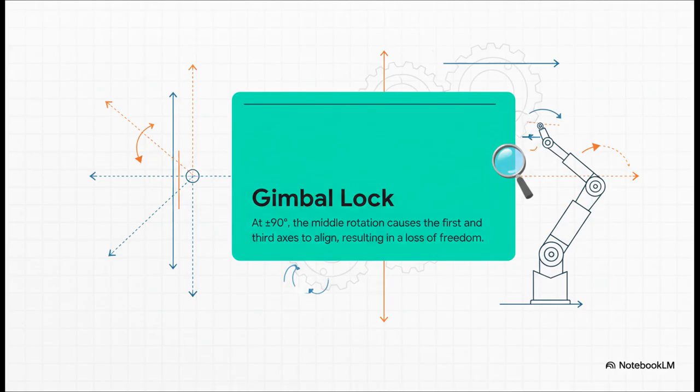But here's the kicker. All 12 of these, every single one, suffers from the same catastrophic flaw. And that flaw is called gimbal lock. This isn't a mechanical problem, it's a mathematical one. It's a singularity in the representation itself, a specific configuration where you literally lose a degree of freedom. Your ability to orient your robot in any direction you want just breaks.